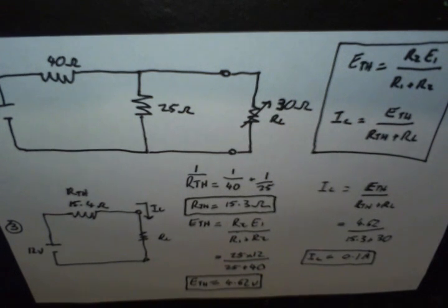Once Thevenin equivalent values have been determined, it is possible to investigate the effect of changing the values of components around the network and how they affect the behaviour of the circuit. This is incredibly useful because complex calculations do not have to be made for each change. It has also allowed for the analysis of networks with sources that are neither in series nor parallel, and for the reduction of the number of components to establish the same behaviour at output terminals.